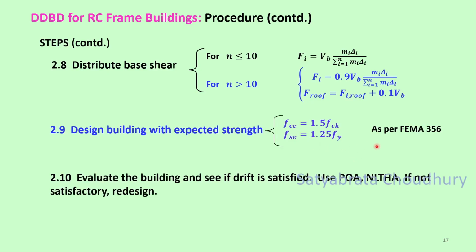This we have discussed. Why expected strength? Let us just tell one line. Because you are making a damage-based design. So at the earthquake damage states, the building will offer its mean strength. It will not offer limit strength or characteristic strength or extreme strength or anything. It will give an average, where average is mean or expected strength. So expected strength is used in the design as well as in the nonlinear analysis.